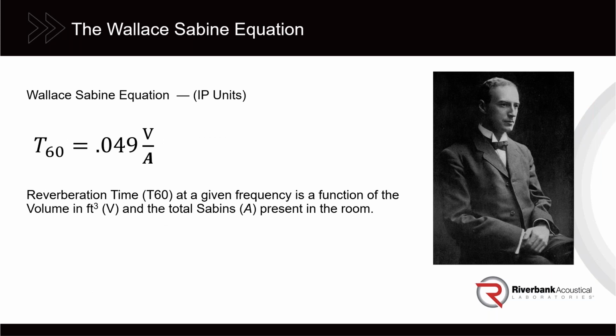Wallace Sabine, who is seen as the founding father of architectural acoustics, created an equation over 100 years ago to quantify or predict reverberation times in a room. With this simple equation he could predict the reverberation time of a room based on its cubic air volume and the total units of sound absorption present in the room, the total Sabins. As the quantity of Sabins increases, the reverberation time decreases.